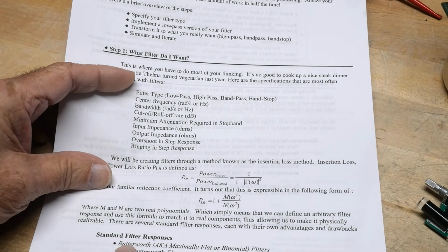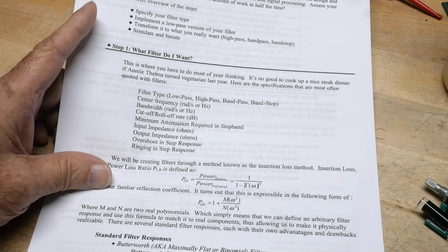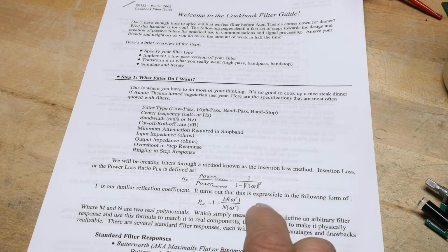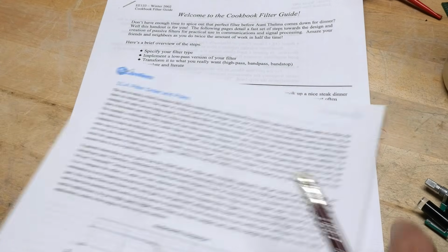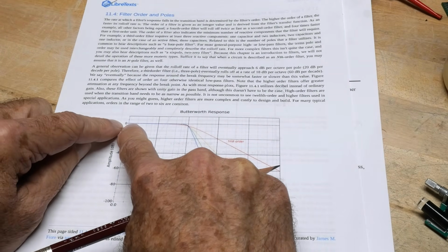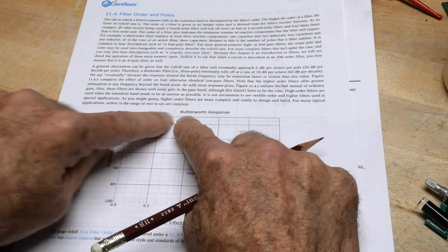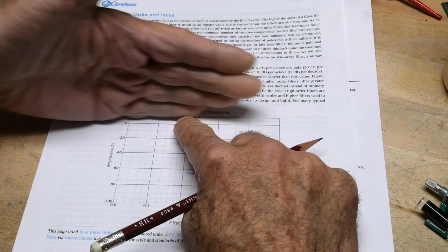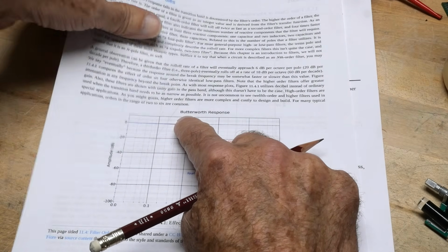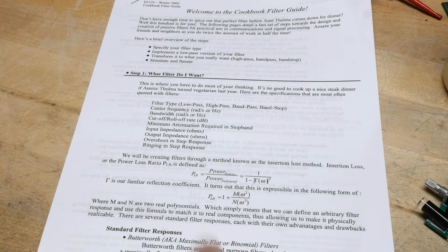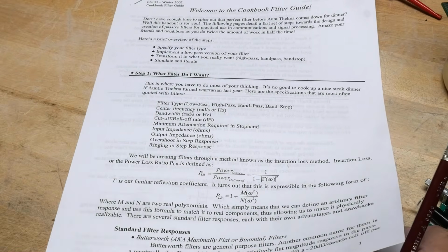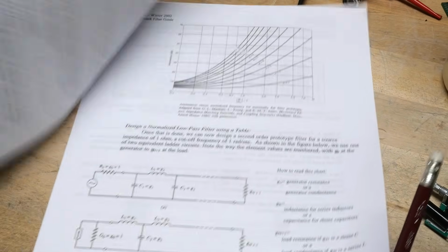One of the first filters you'll learn about is the Butterworth, also known as maximally flat filter. So what does it mean to be maximally flat? So here's a Butterworth filter, and the band pass, where it actually passes things, is very, very flat. There's no wigglies in it. It's a nice, straight, smooth line. Very, very nice. Okay? So maximally flat filter, you would choose a Butterworth. There's another filter that's also maximally flat. We'll talk about it a little later.